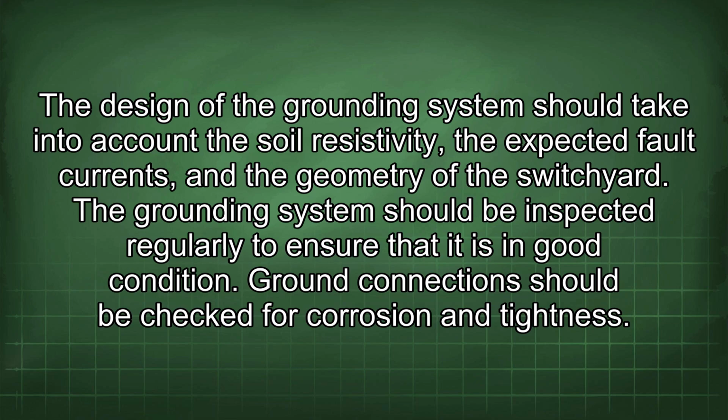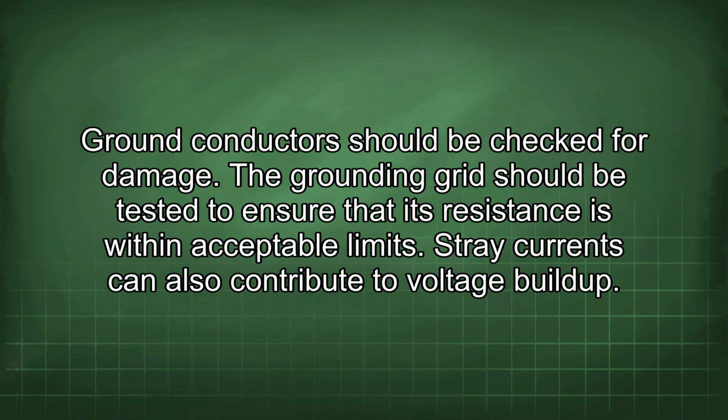Ground connections should be checked for corrosion and tightness. Ground conductors should be checked for damage. The grounding grid should be tested to ensure that its resistance is within acceptable limits.